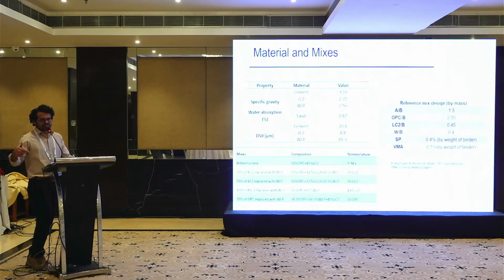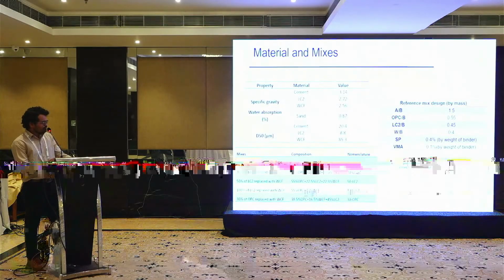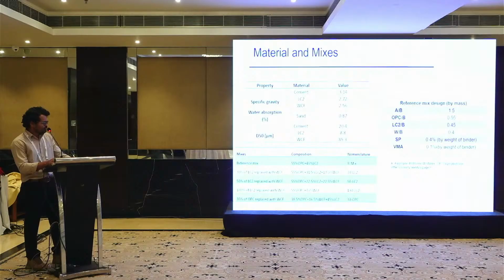I am also trying to use waste concrete fines together with carbon sequestration, so I am trying to do carbon capture with the waste concrete fines. I am replacing LC2 with waste concrete fines at 30 and 50 percent, and again replacing OPC up to 30% after addition of waste concrete fines.